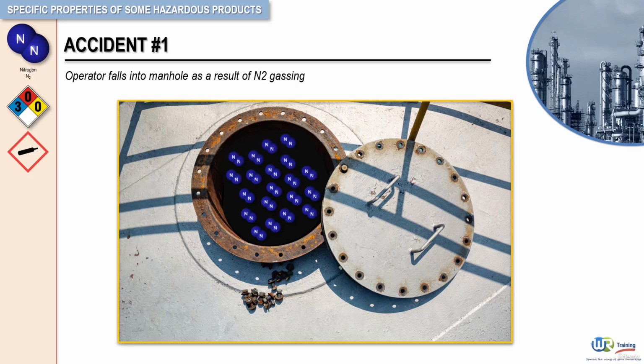The operator was working alone and had not been warned of the oxygen-deficient atmosphere and the necessity to wear breathing apparatus prior to sampling. It is important to recognize here that there was inadequate assessment of the needs and risks associated with taking samples from the nitrogen-rich atmosphere. So please keep this in mind.